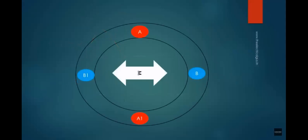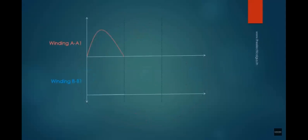So of course, when the magnet rotates by 90 degrees mechanically, the voltage across winding B1 will reach its positive peak, and the voltage across winding A1 will be zero. Therefore, we can say that these two voltages are out of phase by 90 degrees. This simply means that one voltage will reach its peak 90 degrees before the other.